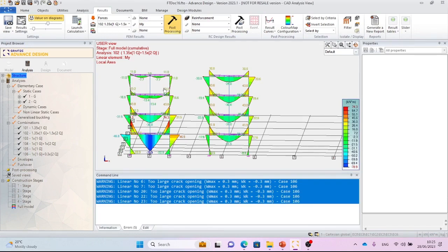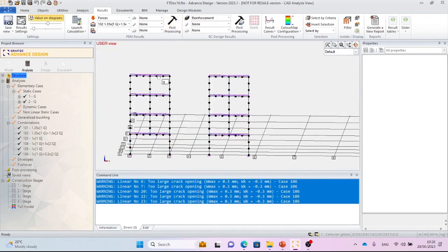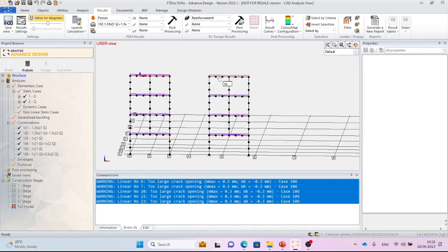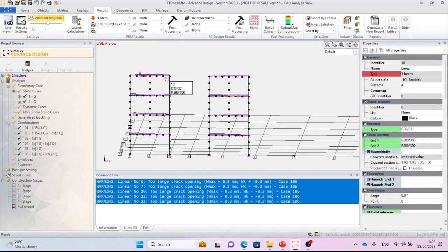So again, we see the same trend, we see the same point of adding the construction phases, because they can be either positive or negative on the results, and basically can affect the structural design. And it's nice to see the theoretical amount of reinforcement needed for this beam. So I'm going to select only the beams of the fourth floor, the ones that seem to have the more difference between them.